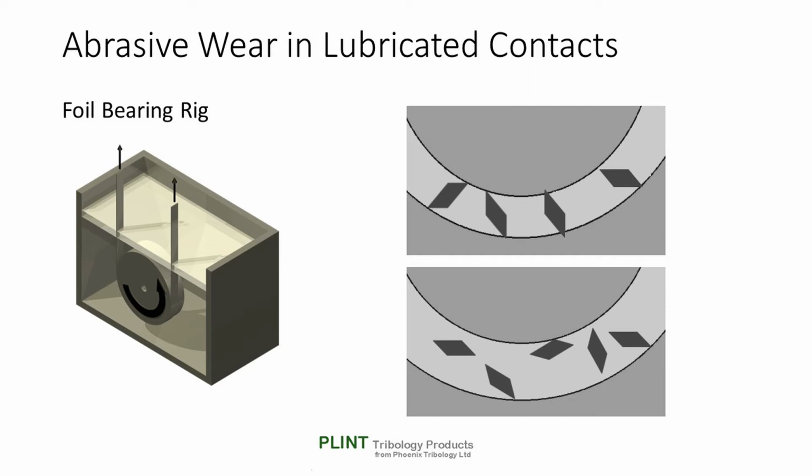Above a certain size gap ratio, the particles are no longer free to roll through the contact, instead being dragged through, generating grooving wear. As with the pitting wear mechanism, the actual load on the bearing is of no relevance other than as a mechanism for setting the bearing gap. It will be apparent that the load on a particle will be a function of the size gap ratio, the relative hardness of the particle and the bearing surfaces, and the number of particles sharing the load. It is not a function of the load on the bearing itself.